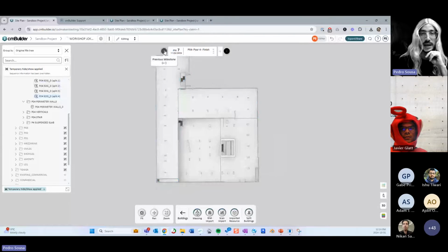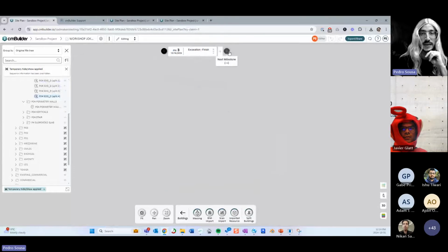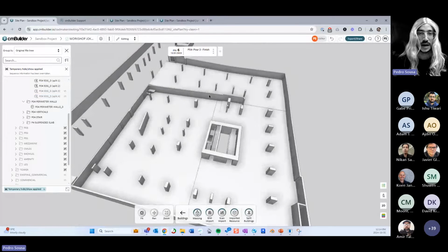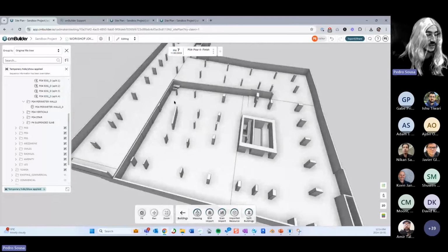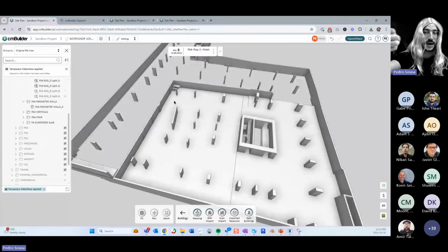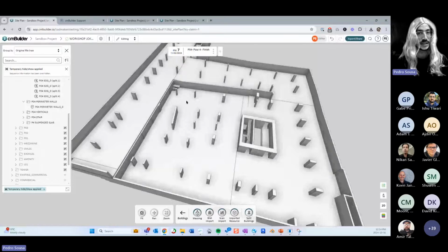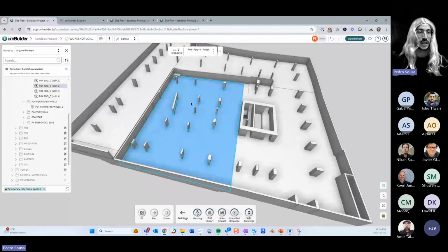So now if I go back and forth, you can see that all the steps of my splitting geometry are now representing those stages of execution for my slabs. Cool. This is one great use case for the tool, where you have big slabs, like your slab on grade, or large areas for warehouses and things like that, because you can now extract, for example, a QTO of this part.